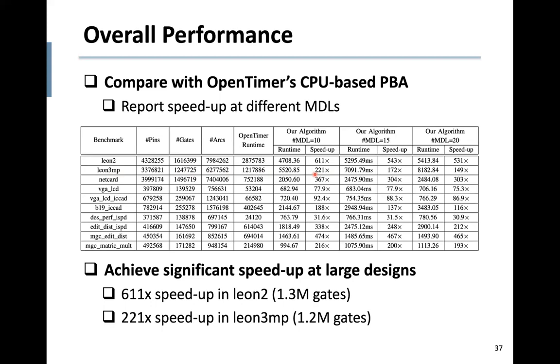The accuracy is strongly correlated. For most of the paths, the traces are the same. We can output pretty much the same result as OpenSTA, but the runtime is significantly different because OpenSTA does not have, I guess, a very good algorithm for generating paths. So it takes several hours.